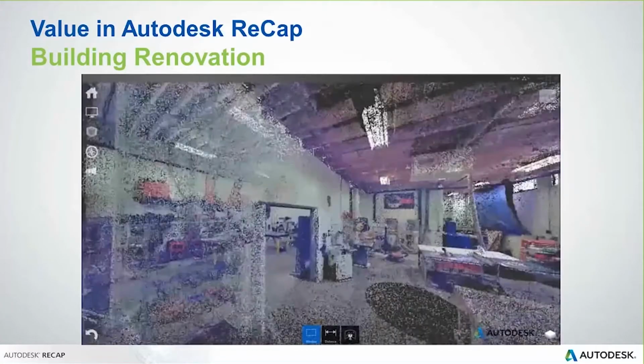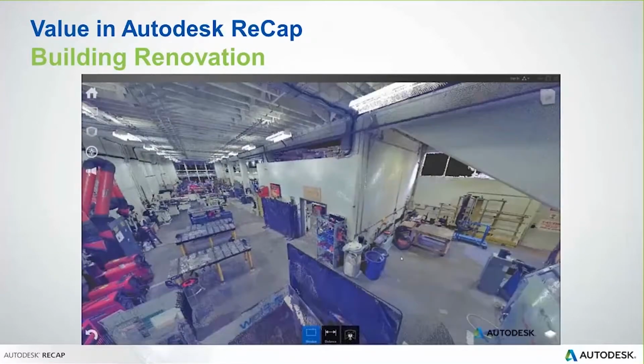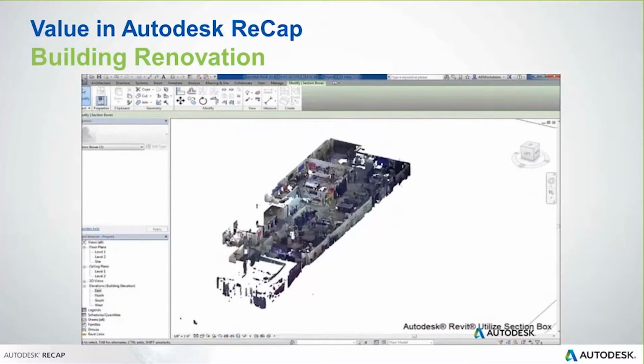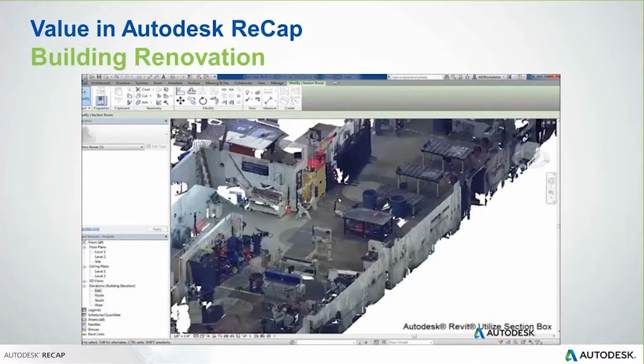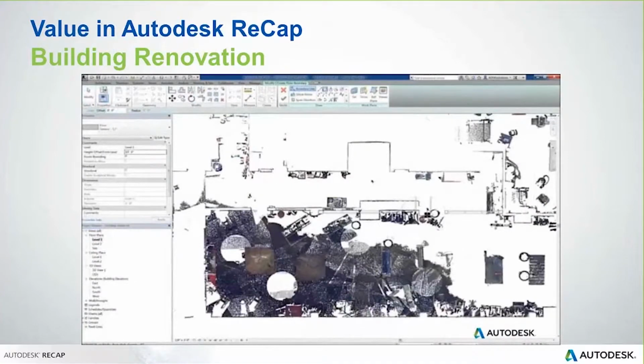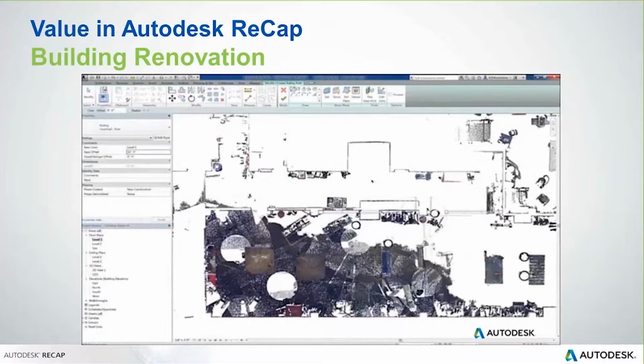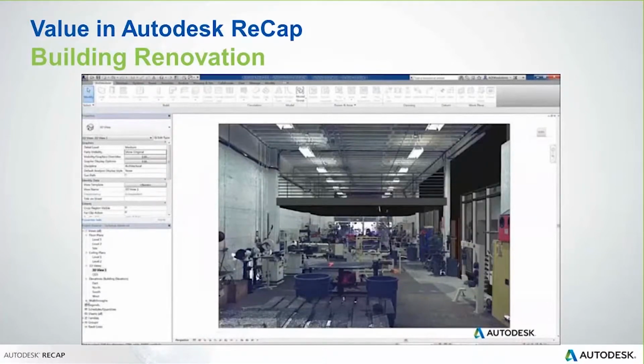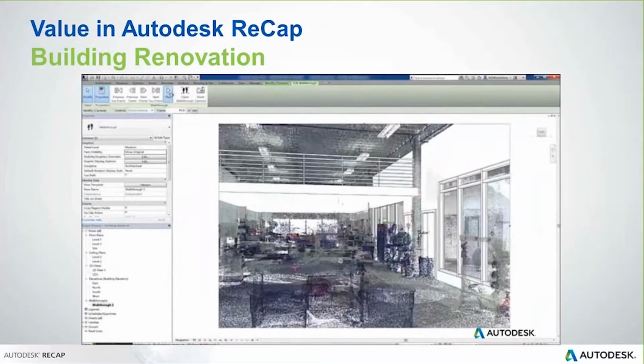We talk about a building renovation. You're looking here at a scan of our tech shop in California, and simply adding some dimensions here. We can check dimensions. We can lay out walls. We can lay out floors, as you're seeing here. And the key is we're actually using the scan as the base model.